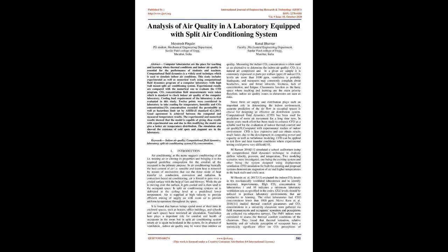CO2 concentration field measurements were taken, which is standard to check indoor air quality of the computer laboratory. Cooling load requirement of the laboratory is also evaluated in this study. 12 points were considered in laboratory to take reading for temperature, humidity, and CO2 concentration. CO2 concentration exceeded the permissible as well as hazardous limit set by ASHRAE standard 62.1, 2013.